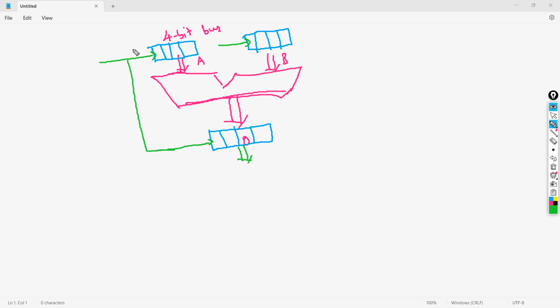Say here, only when the clock signal comes, the data at the input gets captured, and the value at the A bus remains constant, and the value at the B bus remains constant. Then it performs either arithmetic operations, like addition, subtraction, shift left, shift right, or one's complement, two's complement, and then multiplication, division, remainder calculation. So there are n number of things that you might do. Then after certain cycles, your data would be out, right? So this is how we design any circuit.